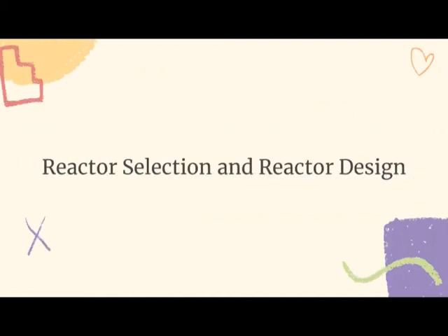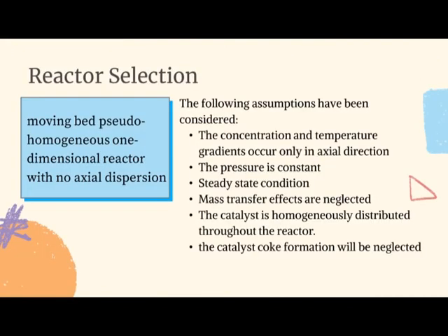Assalamu alaikum and hi, I am Emad Rayhan. I'm going to present the reactor selection and design. For reactor selection, we will be using a moving bed reactor because we are considering the catalyst regeneration process, where we need to withdraw and regenerate the catalyst during the operation of the reactor.